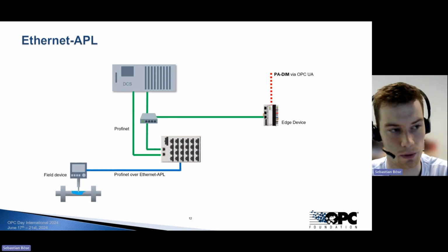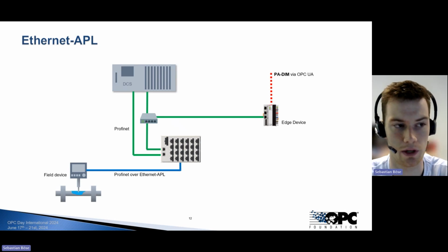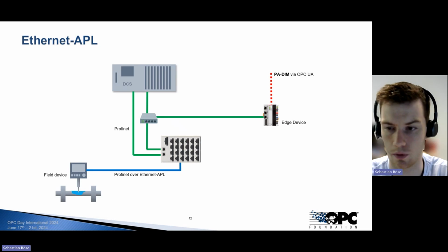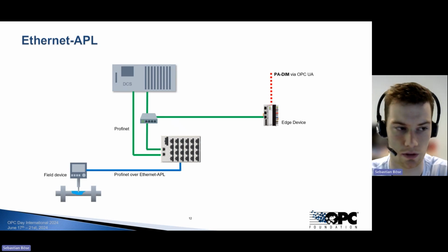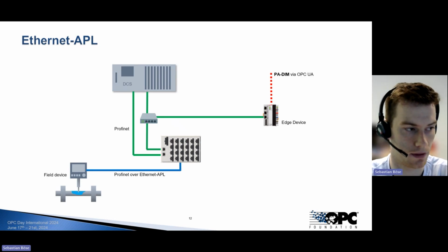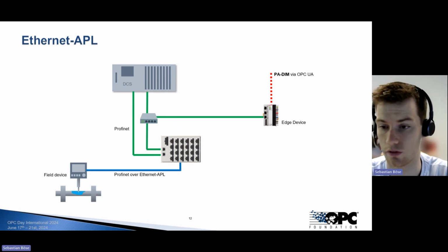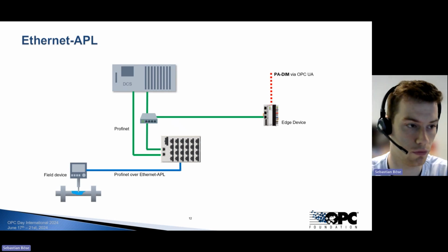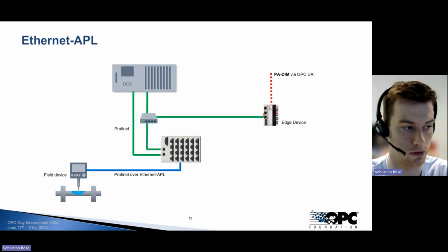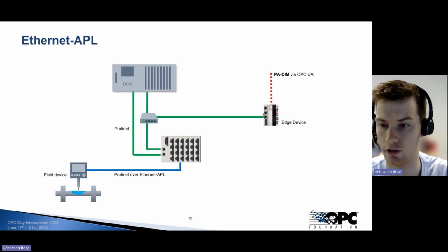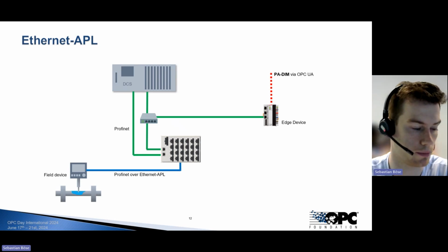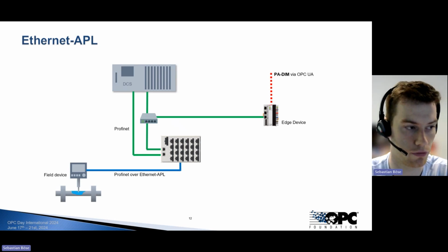And then at the end, it's always the same information model via OPC UA that we want to show to an upper level system. So that's the main benefit, or the main message, that we always show the same information model, whether it's fully filled or just a few variables, to upper level systems, whether it's a pH sensor or an O2 sensor or whatever, and independent from the manufacturer as well.